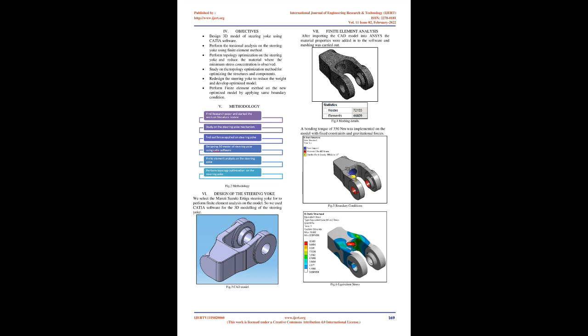4. To implement the universal joint in various applications depending on the functional ability, Dodge and Everton designed the universal joint in reference to the minimum diameter, torque, and angle at which it was transmitted. The failures occurred due to the cyclic uneven torque acting on the joint. 5, 6. Wagner and Cooney proposed a precise guide neglecting the interference and assuming small angles between joints by analyzing the kinematics and strength of an ideal universal joint. 7. Sasaki studied surface texturing of the bearings in the universal joint. Surface texturing involves the implementation of composite materials to achieve desirable properties required as per the application.